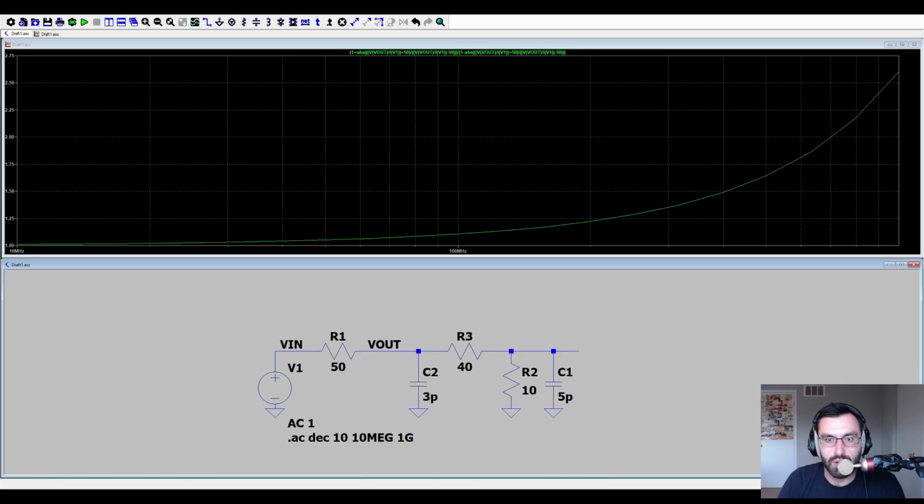Here's the VSWR for the circuit that we're using. Note that it stays below 1.5 out to about 400 megahertz, and it stays below an acceptable 2 out to 700 megahertz. The reason it can do this is we actually switch out 2 picofarads completely, which exist in the 1 megohm path, to bring us up to that minimum 10 picofarad value for use with passive probes.